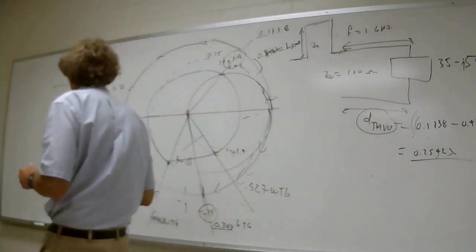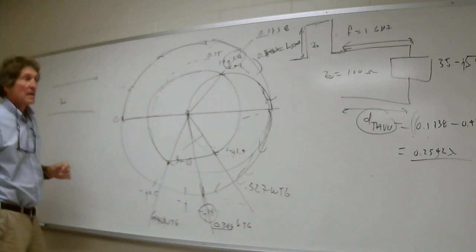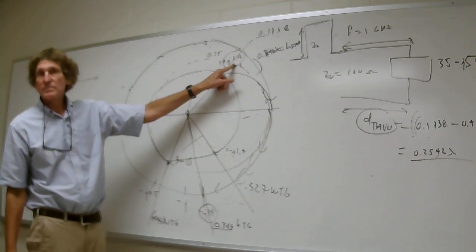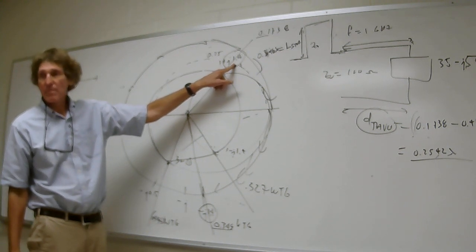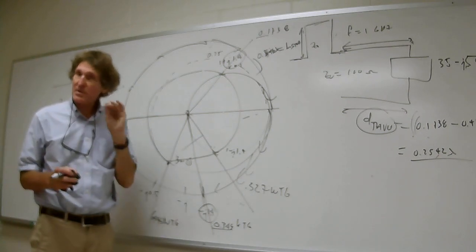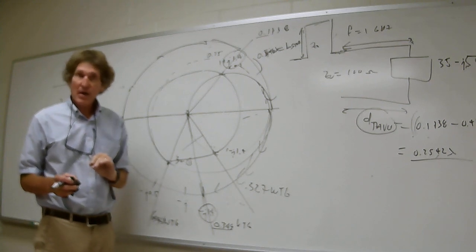Let's go over to this drawing, and I do it the same way. What I need is the normalized impedance to be minus J1.4. Can y'all follow me on this? I'm going to give you a second to write it down. That's what I need to do. I've got to get minus J1.4 in series with it. It's an impedance, correct? So how do I do it?